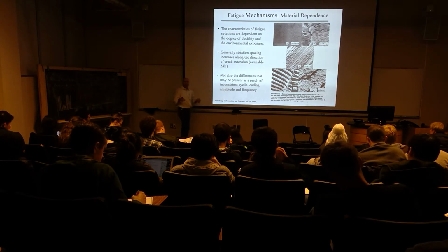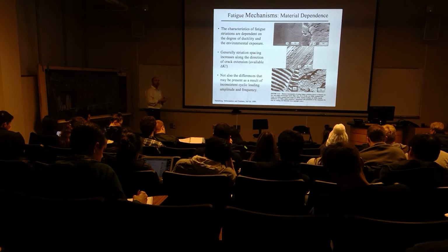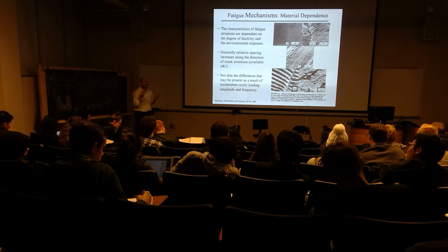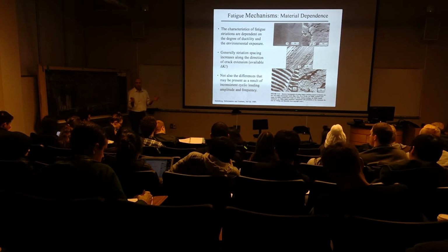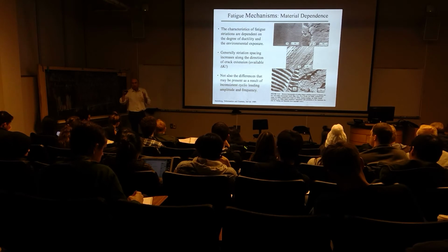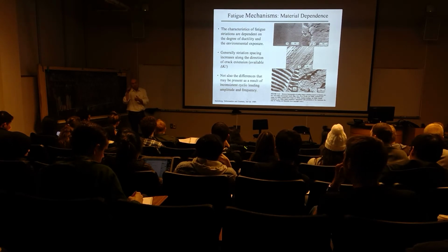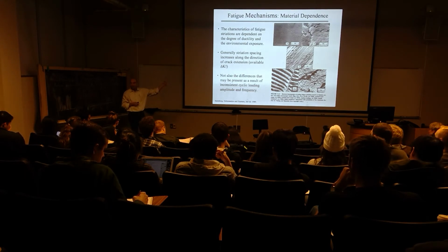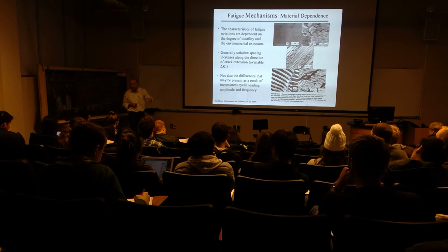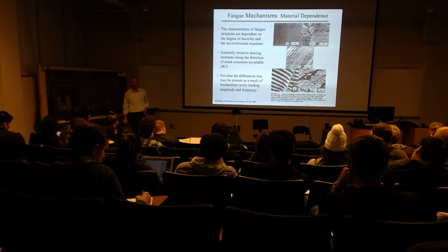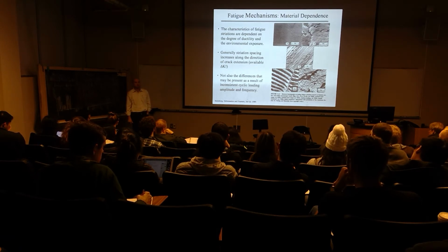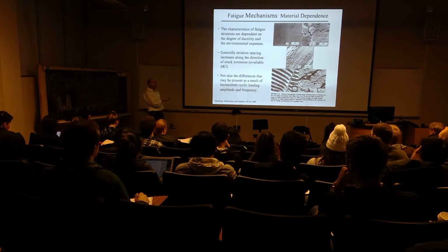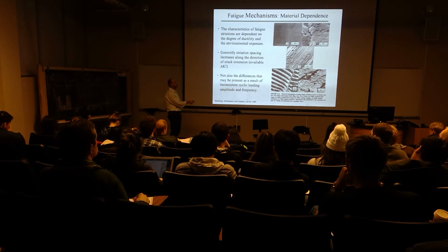So, you know, you could have someone tell you that we believe the cause of fracture was the fact that this structure was overloaded, and then it was subjected to normal loading, and then that one operator in this shift always overloaded. You should be able to tell if that was really the case by looking at crack striations if you know that fatigue crack growth was a part of that fracture. You could trace back to see if that inconsistency told you that there were actually differences in shifts by the way that things were operating.